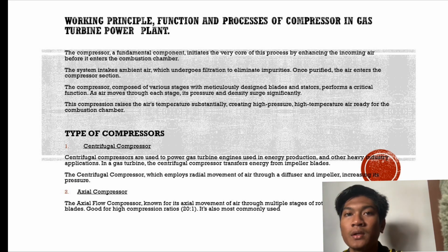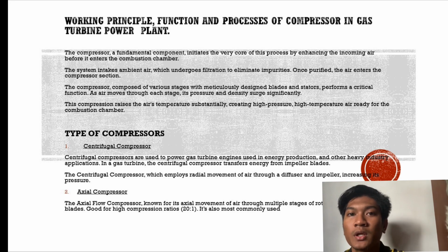As air moves through each stage, its pressure and density surge significantly. This compression raises the air temperature substantially, creating high pressure, high temperature air ready for the combustion chamber.